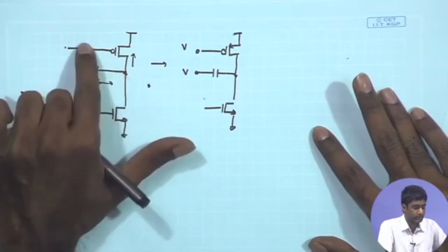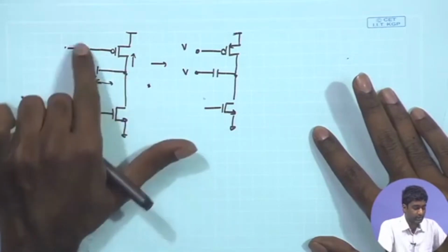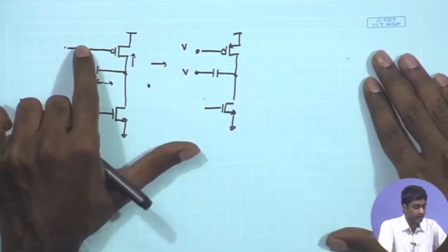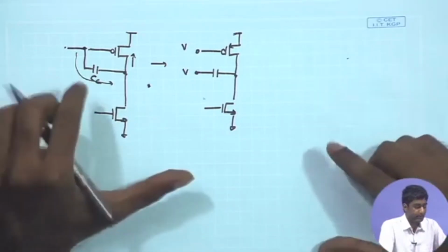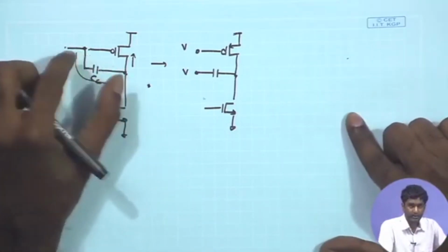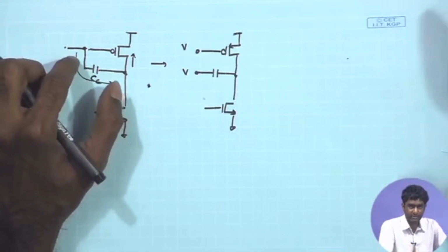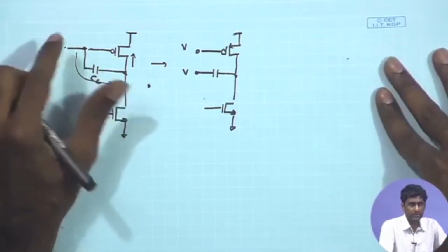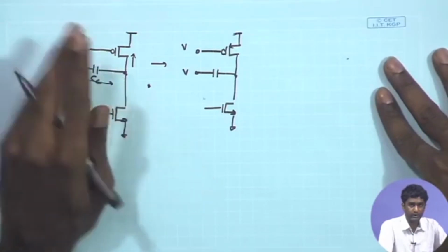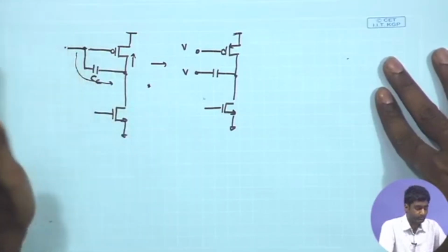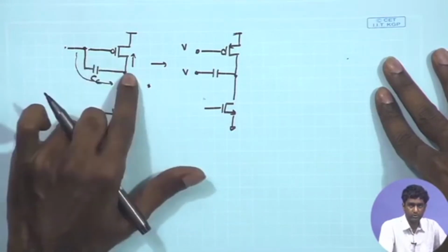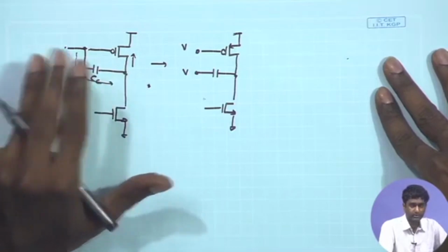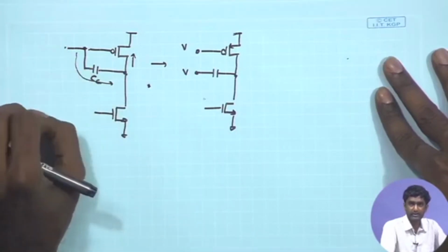So, we are ignoring the signal propagation through these capacitances at higher frequencies, and remember that the concept of Miller effect that we use has an inherent approximation, that the same gain, the low frequency gain, is valid at higher frequencies at which we are applying those capacitances also, which is also not true, because when we apply Miller effect and take the low frequency gain, that is valid for the pass band or low frequencies below the dominant pole of the circuit. As we go towards higher and higher frequency, the gain also reduces, which we don't take into consideration while applying our approximate analysis using Miller effect.